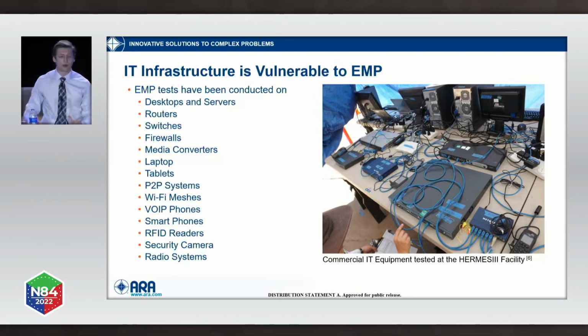One, because it's important that all of the conductive connections that are made to these devices are actually there because they all serve as antennas to drive energy into the device. And also we want to make sure it's working because then when you zap it, if something goes wrong, you could say that you actually broke it because it used to be working.